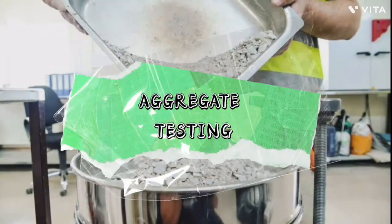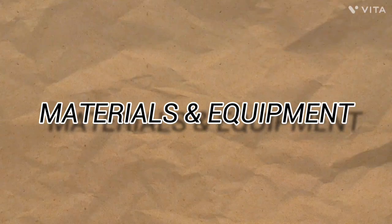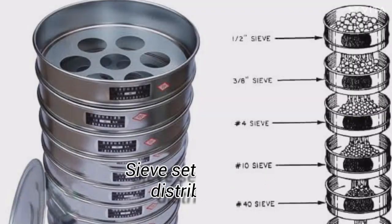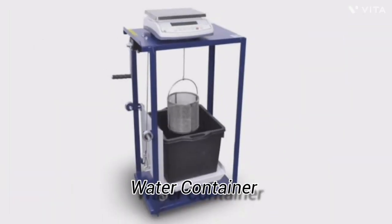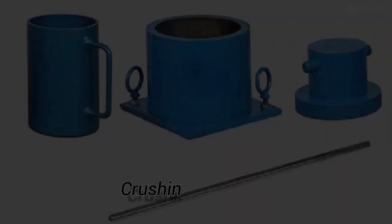Today we will be demonstrating the testing procedures for aggregates, which are essential components in concrete and road construction. We use sieves for size analysis, a balance for weight, containers for water absorption, and a crushing tool for strength tests, essential for evaluating aggregate quality in construction.